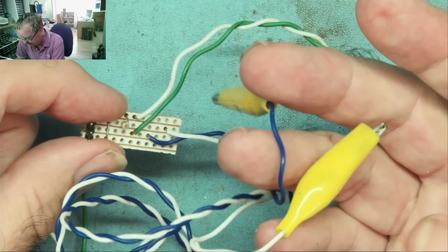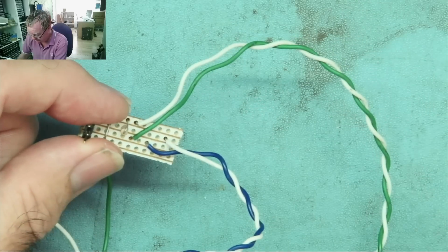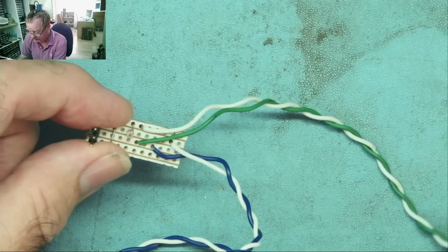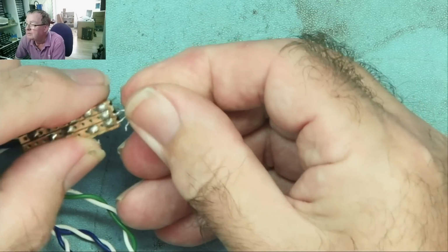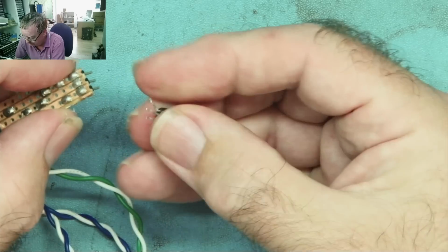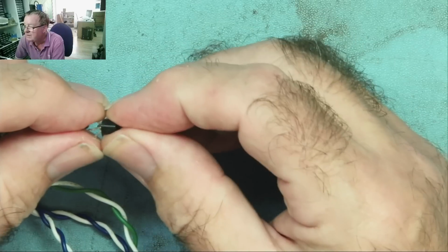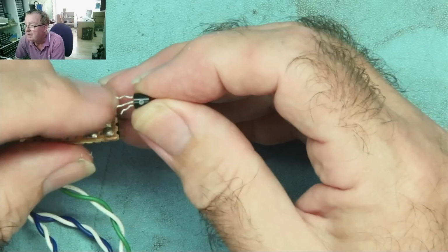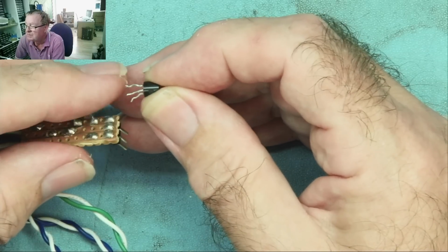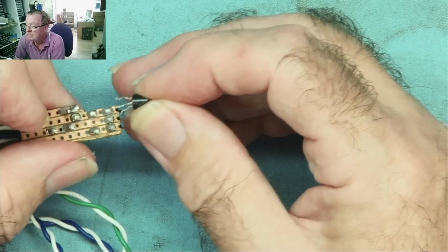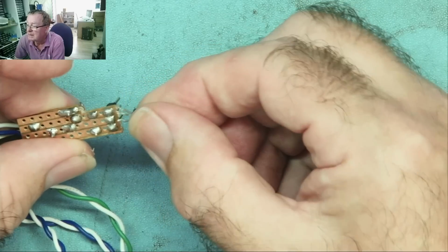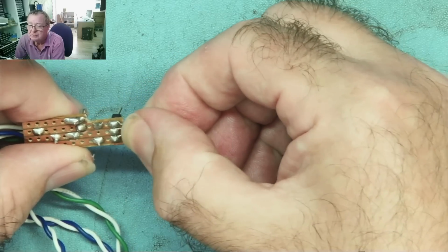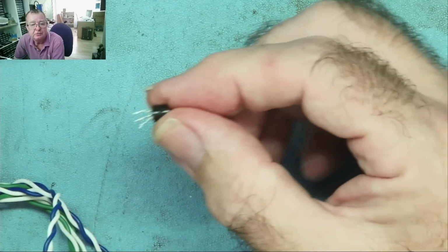So to use the tester, we very simply connect a multimeter on here, we connect the power onto here, and we then just connect our TL431 across the pins, or the tracks if you like. Either this side or this side. It doesn't matter which way you put it round. If you remember from earlier, if you connect the reference to the cathode, the anode is in the middle. This is now a 2.5 volt regulator. So when I hold it against here or against here, the meter will read 2.5. If it reads 2.5, it's good. Let's try it.